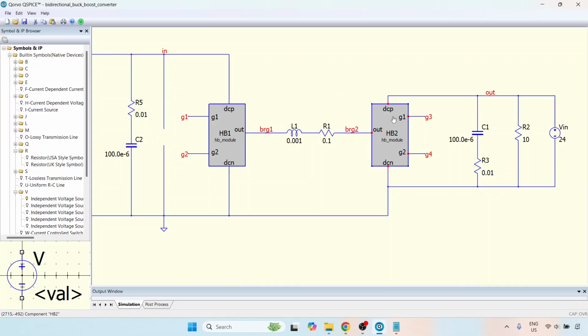And what that means is the device M3 is intermittently operated. Either the device M3 operates and the output supplies energy to the inductor and the input, and when the device M3 stops conducting, or you can say is turned off, then the diode D4 freewheels, diodes D1 and D4 conduct, and the energy in the inductor is supplied to the input.